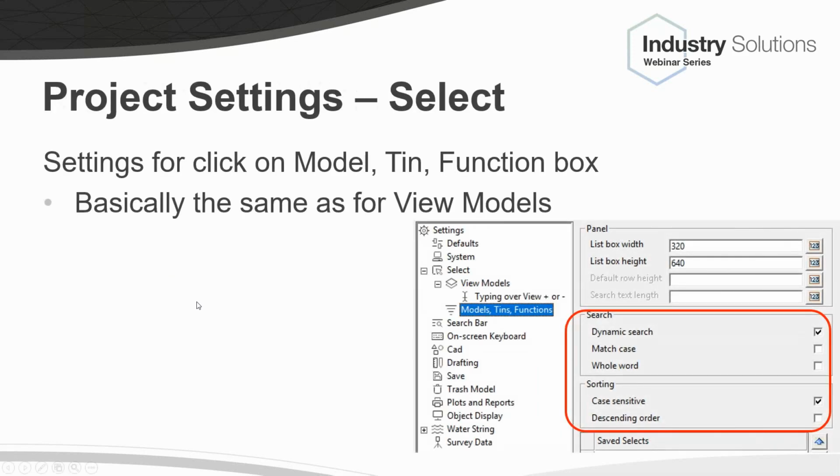Now, one final thing about settings before I leave it: these are all saved away in a file, and it's all documented what the name of the file is. But actually inside that file, you can have more than one set of these things, say a whole profile of them. And you can change that at any time. So if you've got a whole lot of settings set up for, say, drainage, you could have different ones for, say, road design, and just by picking the different settings profile, you'll get the different ones. There are also macro calls, and I think change chain commands to also change those things. So you have one default set, but you can change it any time to another set.